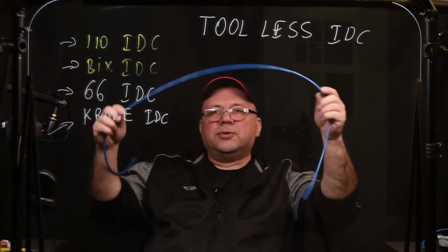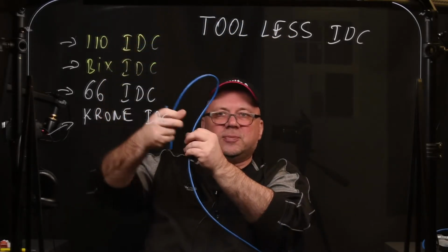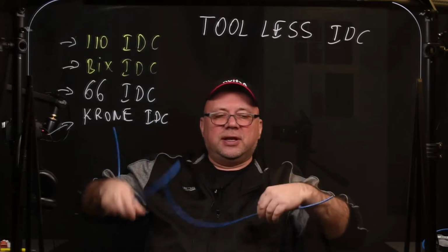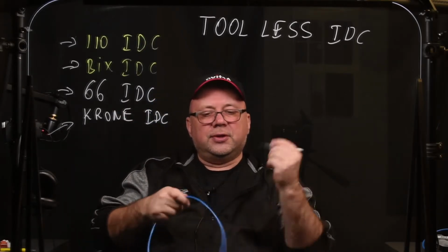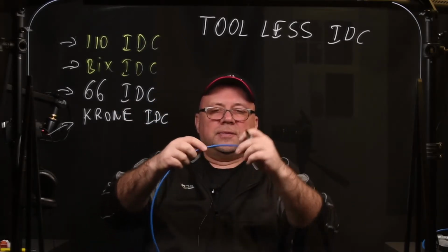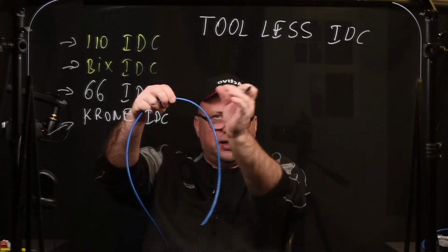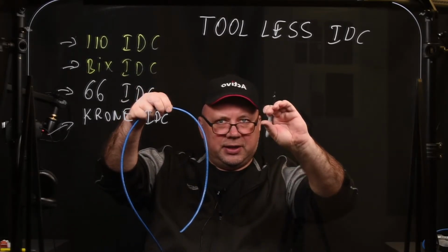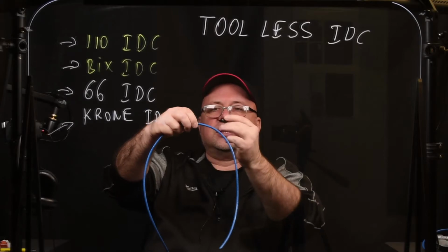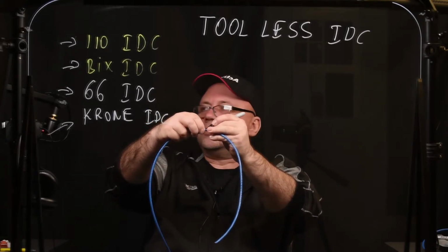So the cables, once you dress the patch panel, are going to have different lengths. So you basically run this wire down, see where it's going to end at the rack location or the patch panel, and say, okay, we need to strip it this much.